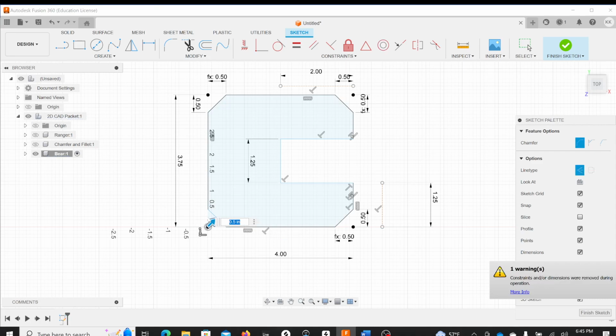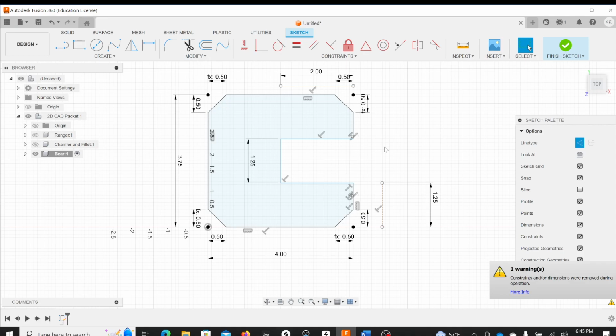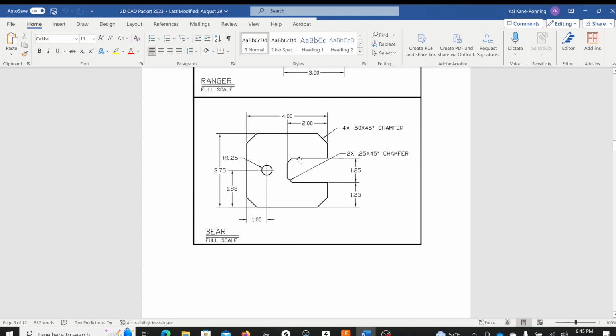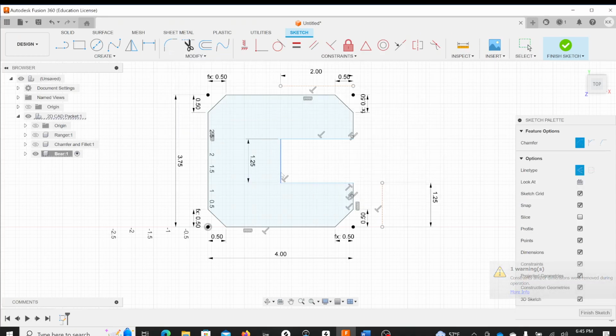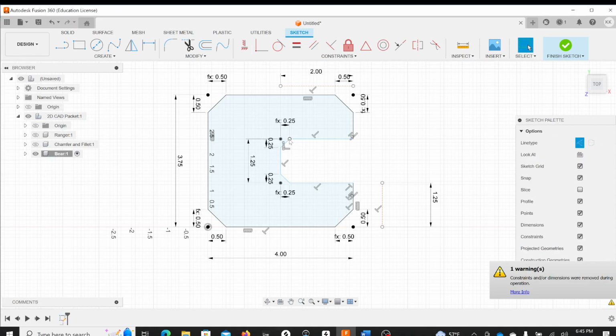And finally, I've chamfered all of those, so I'm going to hit enter. Cool. However, we still have two more to chamfer. 0.25. Okay? So I'm going to go modify, chamfer. Boom. 0.25. And if I don't hit anything yet, and finally hit enter now, it will do that for me. So that was really fast in terms of chamfering all of these edges.